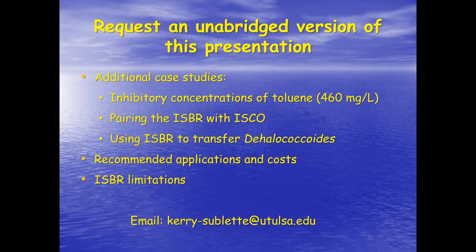Any estimation on the observed radius of influence with these bioreactors? Great question. I can tell you that one of the case studies in the unabridged version of this presentation, which I invite you to request, involved toluene, where we had a fairly large, fairly shallow plume of toluene, and we had 6 of these in situ bioreactors deployed at this site.